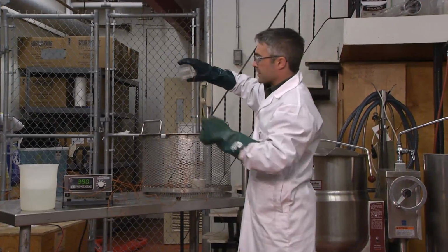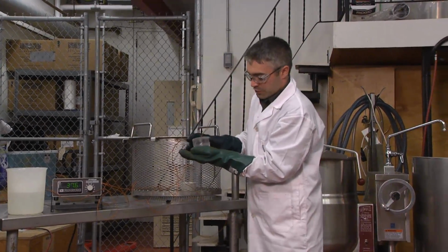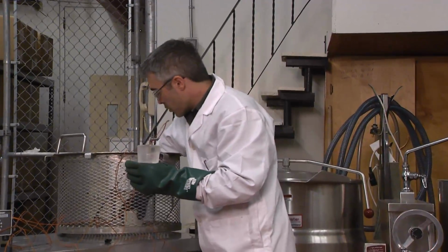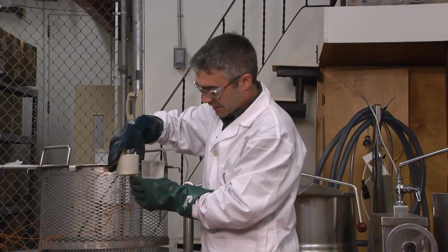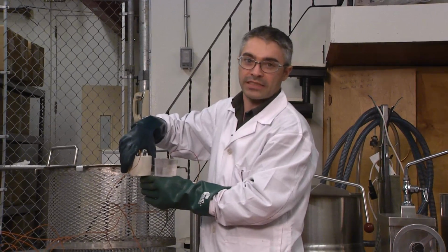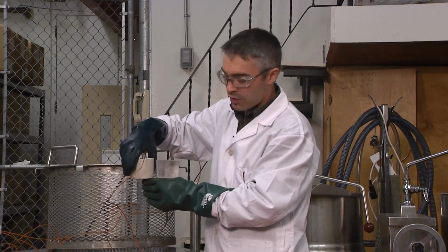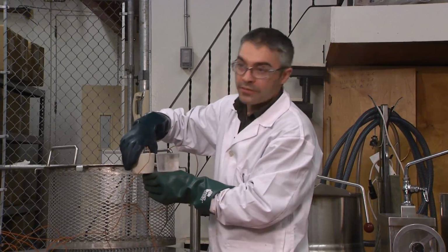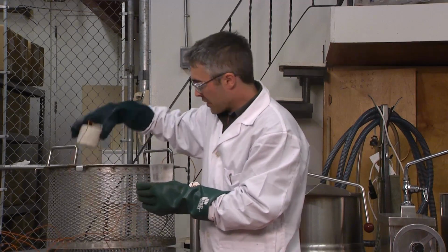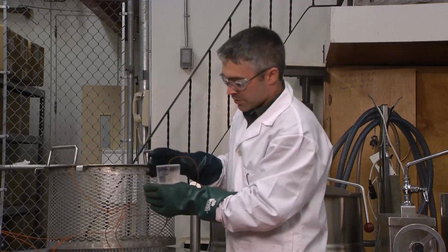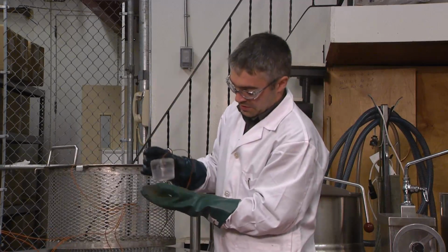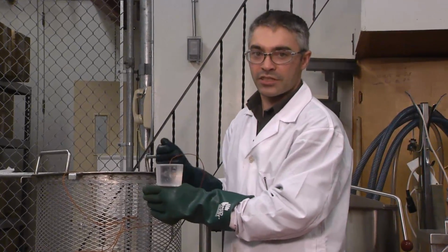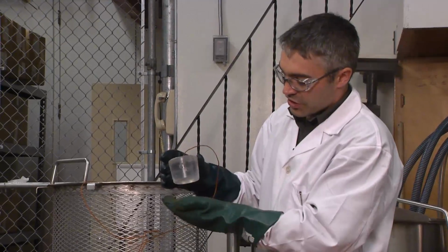Each one of the shape factors given to you will be made of one of two materials, either a high density resin or a low density body fill. Each one of these will have different thermal characteristics. Part of your job in your report will be to determine what the thermal diffusivity or conductivity of each material is for the object. You'll be aided in that you'll have several different shapes. These will be your cylinders. You also have spheres and your slabs, and you'll have thermocouples positioned at different points.